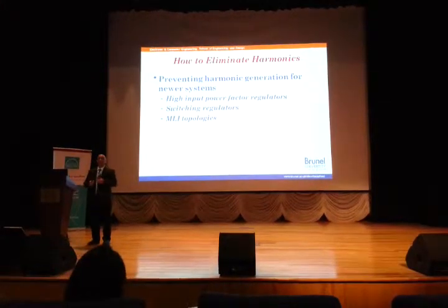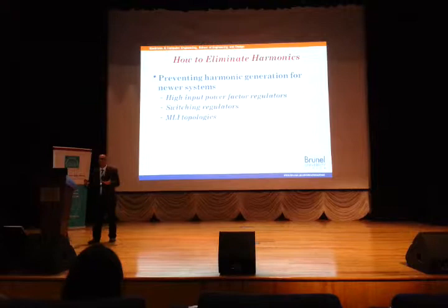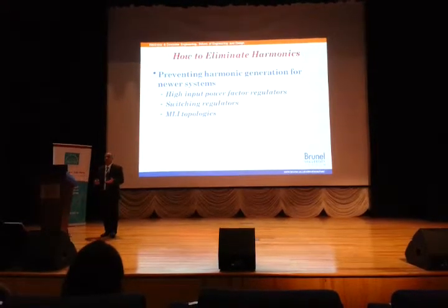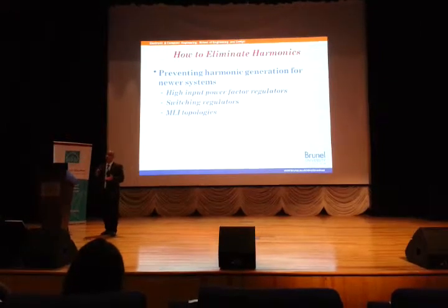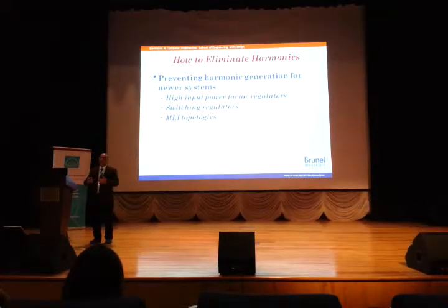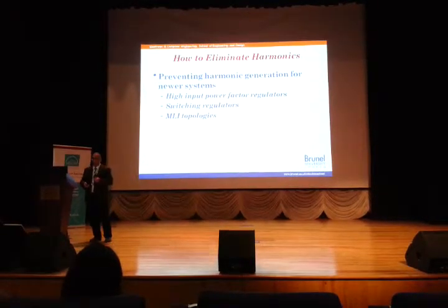Or we have multi-level inverter topologies. Multi-level inverter topologies are a new type of inverter. Over the last, say, 5 years, there have been a lot of technologies there, okay? They try to avoid high switching frequency so that they can reduce the switching losses, and at the same time try to achieve as sinusoidal a waveform as we can.